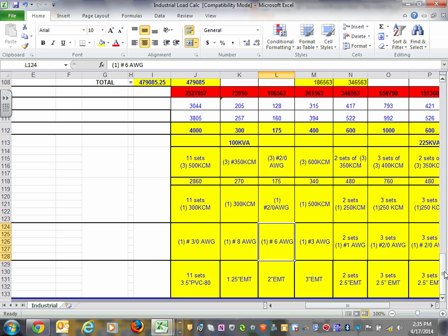Then you add MC cable. Only MC if we're doing a project. We don't use Romex, I hope, or AC cable. Add the MC to the mix: EMT, PVC, and MC cable, and you're up to 95% of your wiring methods in most of the building. The rest is flex to tie to the equipment and maybe rigid in certain areas. So that's why in the service, we're going underground. We're going with a 4,000 amp switchgear. Schedule 80 is the best.